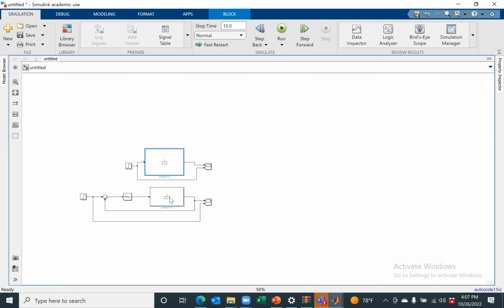So what do you do? You do proportional plus derivative, which means as you start going closer and closer, for example, your friend is walking, and as you start approaching your friend, and you see the velocity is decreasing, the difference is decreasing, you actually start decreasing the proportional effort.